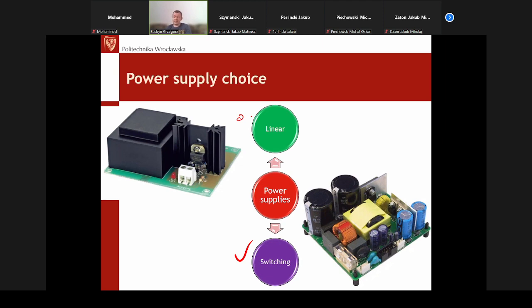We have instead a very nasty 100 hertz or 120, depending on the region in the world, ringing. But putting this aside, the linear regulators are tougher to break. That's again, from a practical point of view, not negligible, I'd say. In case of switching regulators, if they have security circuitry included, then that's fine.